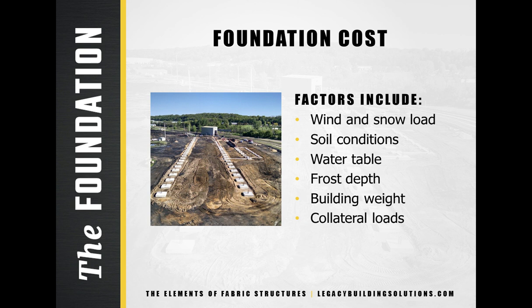The cost of a foundation is dependent on the building's size and location. Factors that influence the foundation design include environmental factors like snow and wind, soil conditions, water table and frost depth. Additional forces include the weight of the building and collateral loads. A thorough evaluation of all these factors is needed to assess and design the best foundation option for each building. Because ground compressibility can lead to excessive settlement differentials, similar or even identical buildings may require completely different foundations at different sites. Once the building materials are in place, it's time for installation.